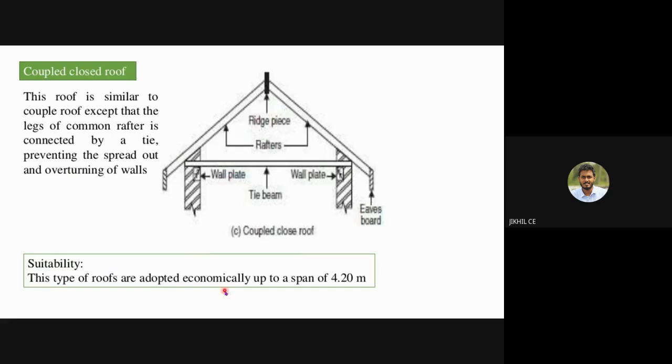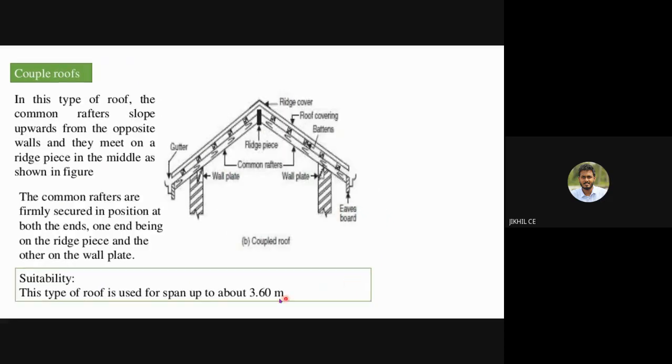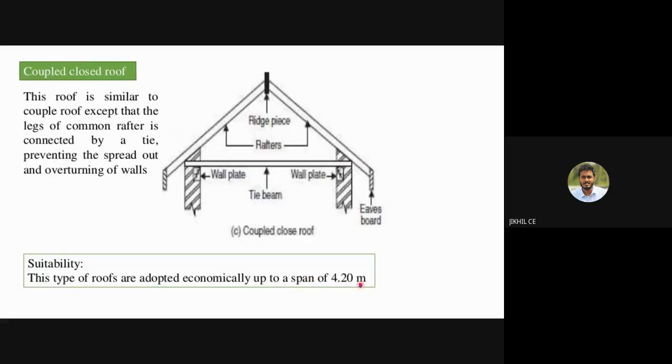So this can be used for spans up to 4.2. Previously it was 3.6. So for more span, you should provide a tie beam. It's the main takeaway.